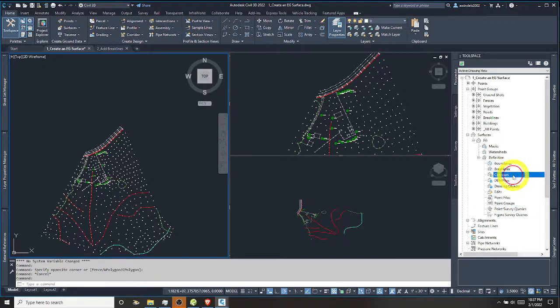Contours, very similar, elevated polylines that basically map our surface exactly how those polylines look. So it forces our TIN to align with these contours. They have to be elevated, so each polyline or 3D poly, they have to have an elevation inside of them. Otherwise, this doesn't really work.